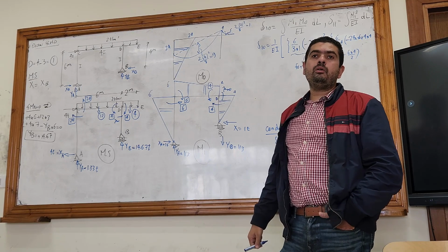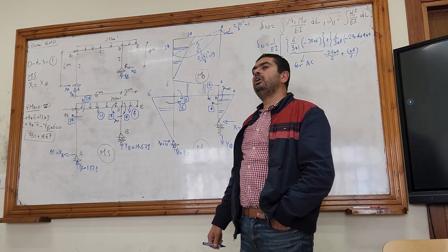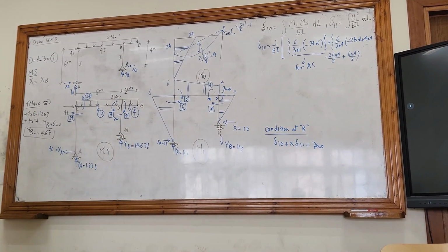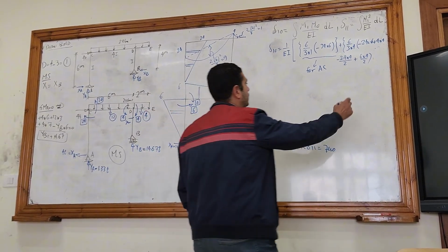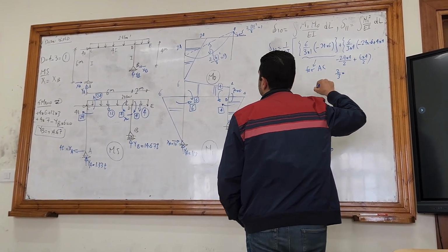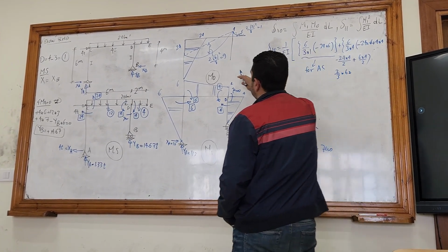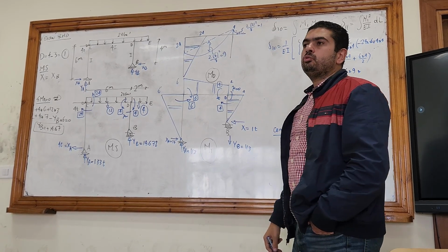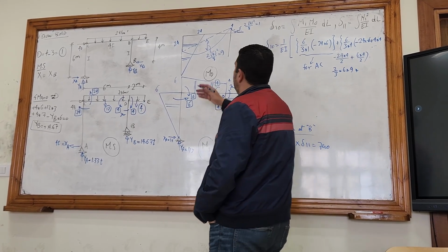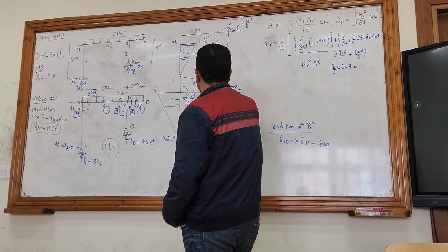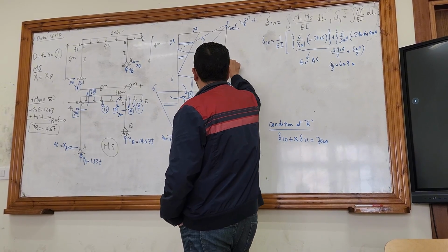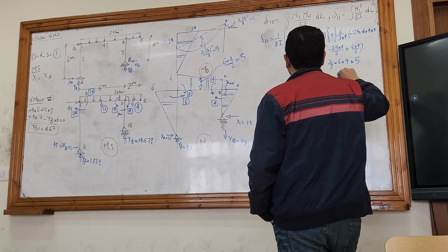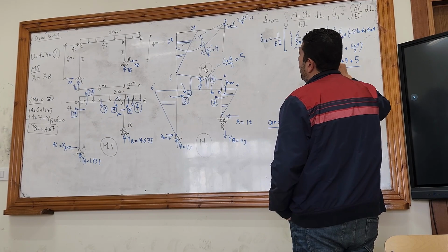The second integration, the trapezium with the parabola. Okay? What is the rule of the integration of a linear diagram with a curve, a parabola? It's the area of the parabola. What is the area of the parabola? 2 over 3, the base, which is 6 meters, multiplied by the height, which is PL squared over 8, which is 9, multiplied by YCG. What is YCG? It's the intermediate value in the linear diagram, which is 6 plus 4 divided by 2, which is 5, right? So it's 5. And then divided by the I factor, which is 4.